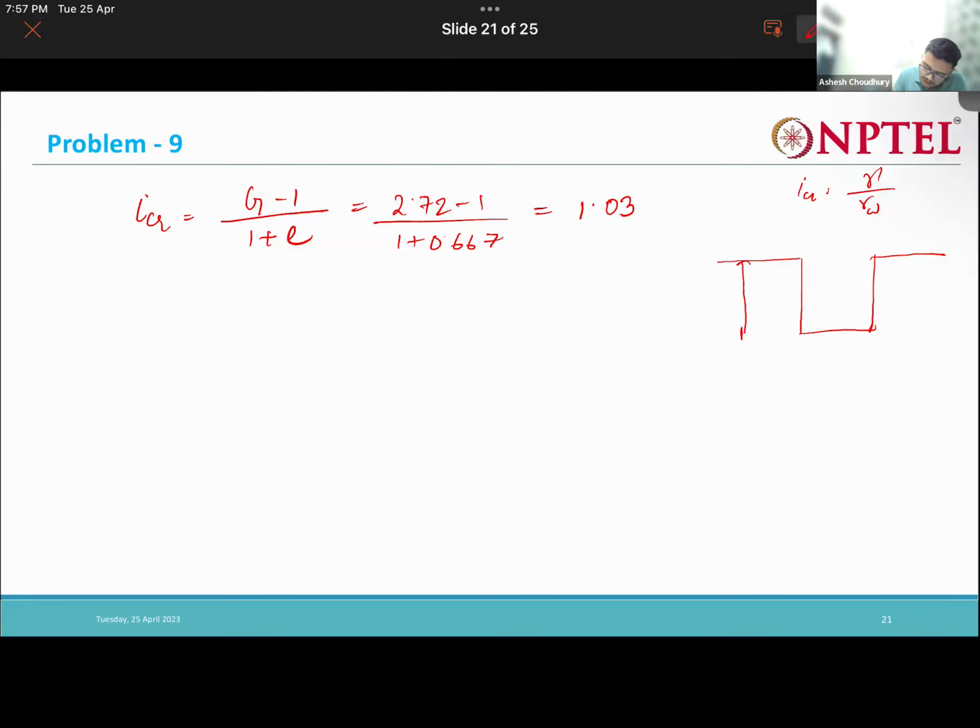Hydraulic gradient will be such that the effective stress will become zero. That means soil will have no strength there. So if you step over that part, the soil cannot hold you, and you will go inside that soil. That is quicksand.